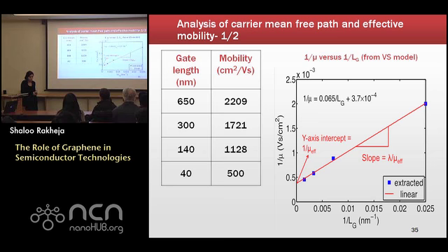What these people have done is they measure their mobility in a big channel device. So what they measure is an effective mobility, and sometimes people also do short channel mobility measurements, but I do not have any confidence in the way they extract their mobility for a short channel device, because there is this ballistic mobility effect which needs to be incorporated, and a lot of the time experimentalists fail to account for that. So are these contact effects included?